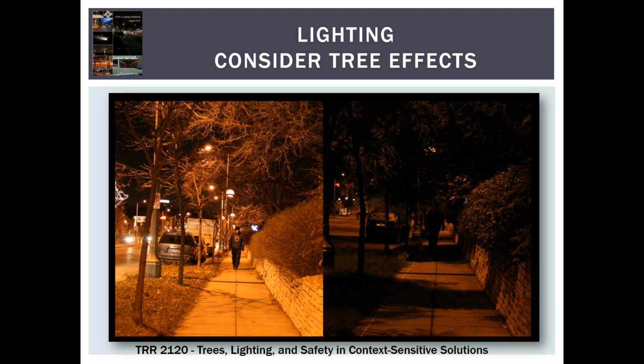When a roadway or pedestrian lighting project includes new or existing trees in close proximity to the lighting, an additional light loss factor should be included in the design to accommodate the light loss due to shading from the leaves. Insufficient research is available at this time to quantify the factor with precision, but an additional 10 to 20% of lighting is probably going to be reasonable.